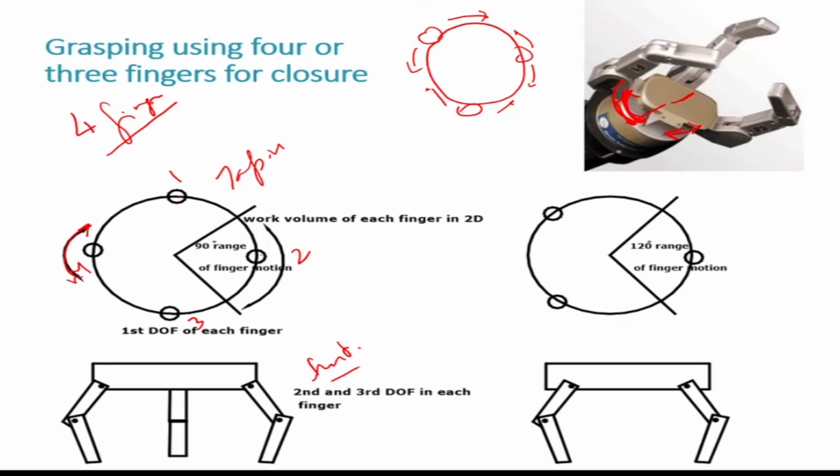The question being asked here is, in order to have form closure of this object, how would you place your fingers? Where would you place your fingers? What is the motion plan? With 4 fingers and point contact without friction, we can obtain form closure. On the right-hand side, we have point contact plus friction. In this case 3 fingers are enough. So 3 fingers can be used to obtain force closure.